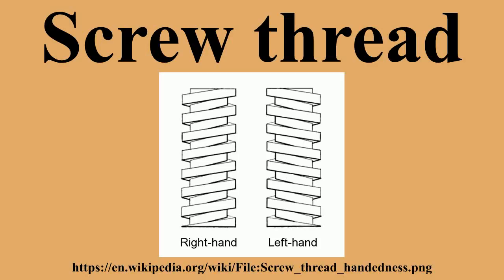Thread limit, a pitch diameter limit, is a standard used for classifying the tolerance of the thread pitch diameter for taps. Imperial H or L limits are used, which designate how many units of 0.5 mils over or undersized the pitch diameter is from its basic value, respectively. Thus, a tap designated with an H limit of 3, denoted H3, would have a pitch diameter 0.5 mil times 3 equals 1.5 mil larger than base pitch diameter, and would thus result in cutting an external thread with a looser fit than, say, an H2 tap.